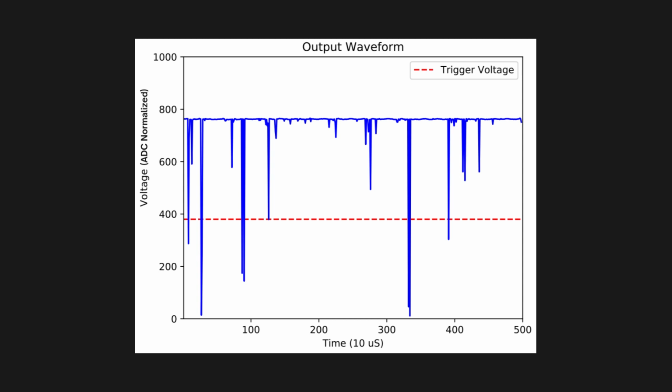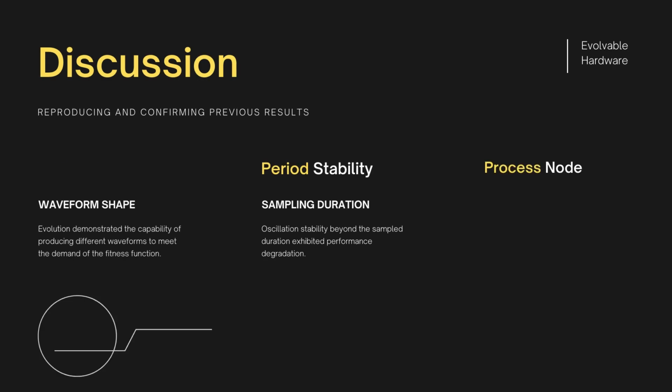Further, the period between pulses exhibits little or no discernible pattern, yet somehow the circuit produces roughly 1,000 pulses per second. We decided to test environmental effects by heating and cooling the FPGA, as well as uploading the evolved circuit to 3 different FPGAs of similar make and model. Heat caused a dramatic increase in frequency before halting at some upper limit, and cooling delayed all circuit output for several minutes until the FPGA achieved its standard operating temperature. And when uploaded to different FPGAs, 2 of the 3 failed to output a signal at all, while the third output a signal of completely different frequency.